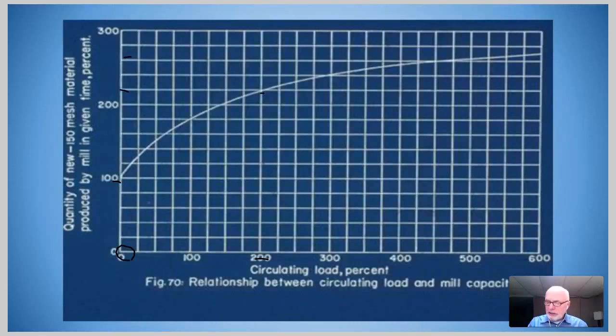A lengthy residence time is needed to grind all the way to the product size in one pass. The mill discharge itself would be 80% passing the P80 size. So at least near the discharge end of the mill, only 20% of the power is going to the grinding of coarse plus P80 size material, and 80% is being wasted. Depending on the size distribution of the mill feed and the back mixing conditions, an extremely large portion of the mill power is being wasted.